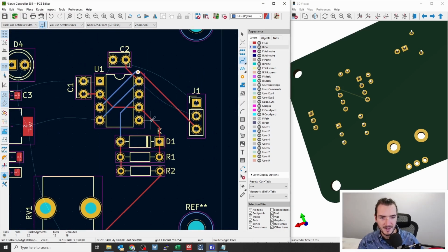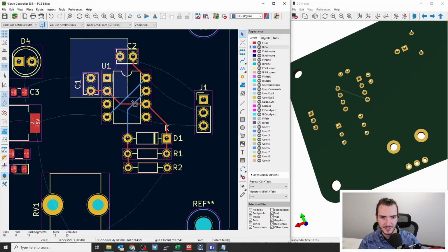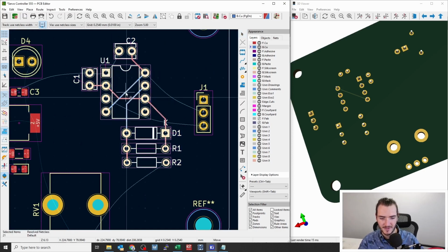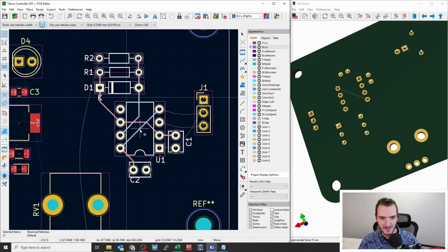You know, here it might have been better if I undo those and I actually take this whole block and rotate it. So I'll remove this line by striking U. U selects the whole trace and delete that. I could actually rotate this whole circuit block. And this is part of the circuit layout process, is maybe it's better for me to do this.